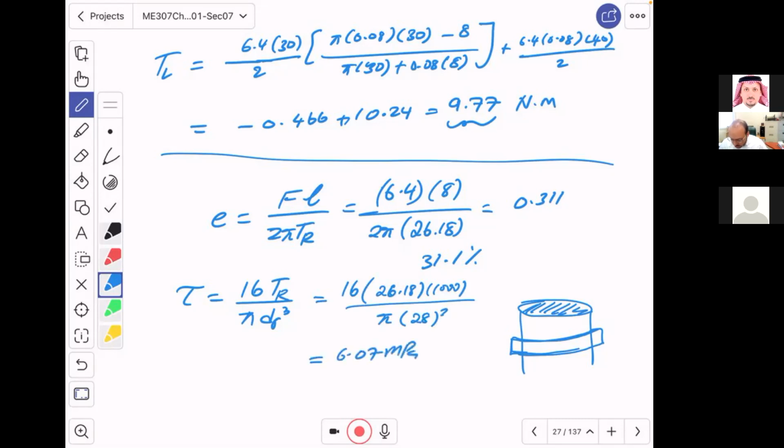This is not a lot, but if you use only the lowering torque, it is probably going to drop by 3. So both stresses will be applied. When you raise the screw, you will apply 6.07 of shear stress, and when you apply the lowering torque, you will apply around 2 point something.